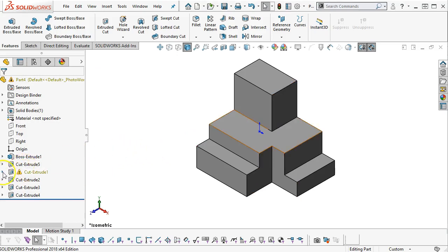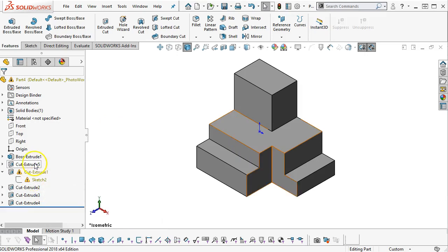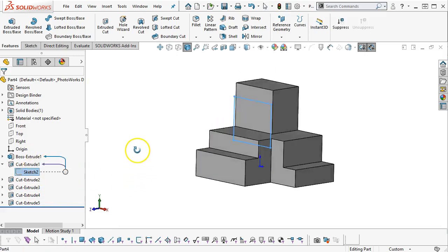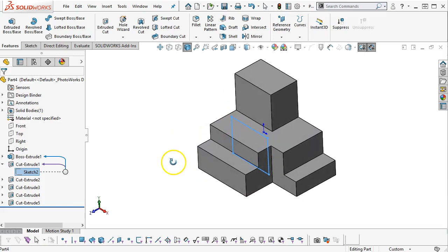All right, so there was one relation, or two relations. But as we go through, whatever got removed off of that face, we could go back and pick up. So as long as you're careful, that's pretty much what those arrows are telling me, that there's a relation back to it. But because I've changed the geometry related to that face, basically this face was modified, there's going to be an issue with that sketch now.